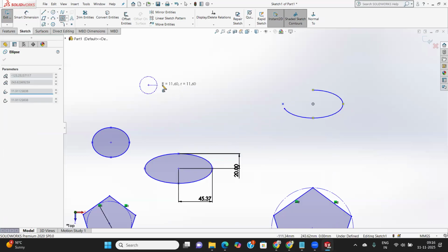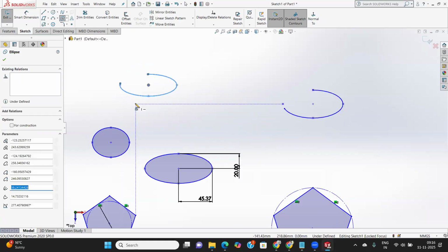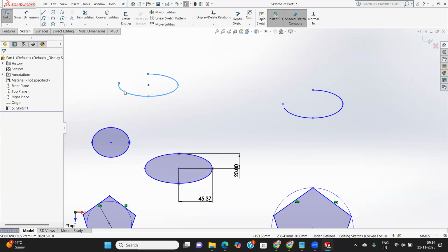Simple. First of all, center point, then first radius, then second radius, and after that for the first radius, you can mark the angle to where you want to show it. Then this is your circle. You can also change this to 40, 15, and if you need the angle to be 270 degrees, then you can write here 270 degrees, and this will be made. If you want to write 180 degrees right here, you can get this type. Here you can change anything and make the arc.